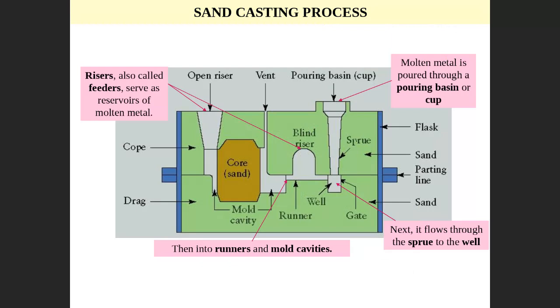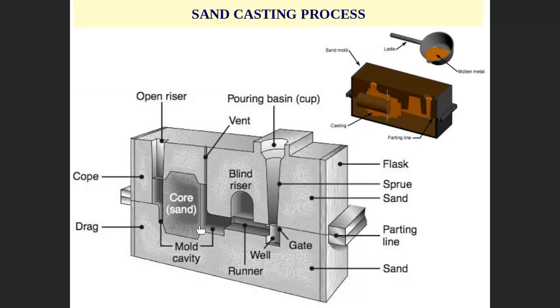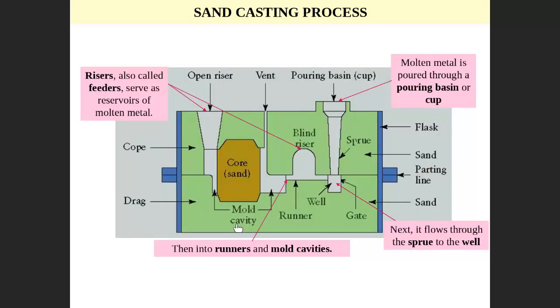Right. This is a mold. We call it a mold again. These are two views, and this is a 3D view. This is a two-view drawing of the same thing. Let's agree now: this is a mold. This one is a flask. The blue one is a flask, made of metal maybe. So this is a flask container. This is the upper and lower part. We call them cope and drag. So this is the cope, and this is the drag, right? Upper and lower, cope and drag.